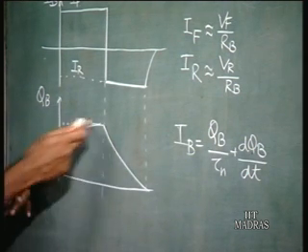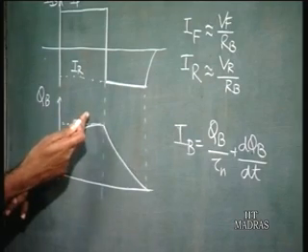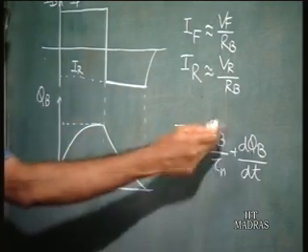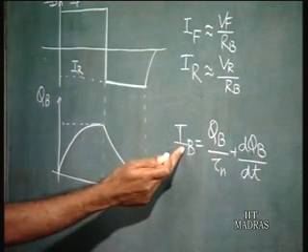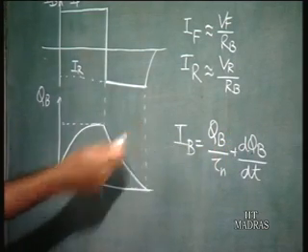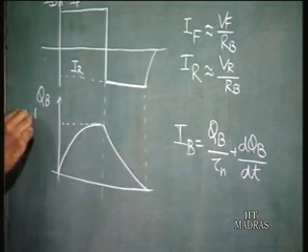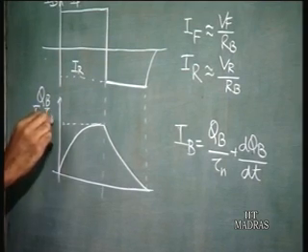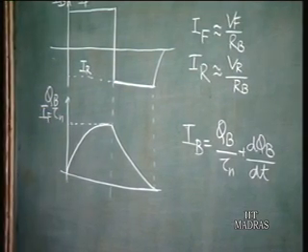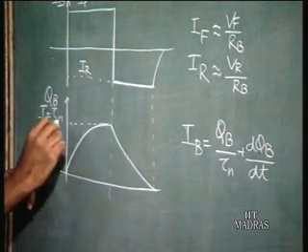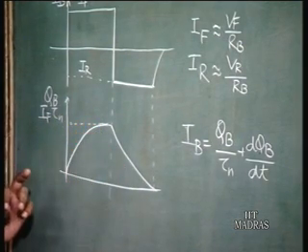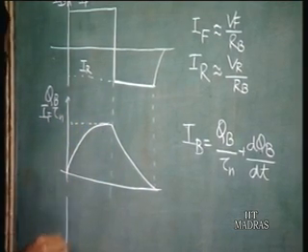Of course, what it means is when forward current is flowing, then in the steady state once it reaches here, this goes to 0, and IB is equal to IF. So, QB is equal to IF tau n, and this is the peak value and then it goes down.